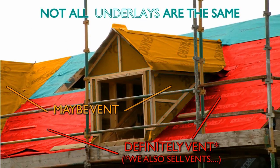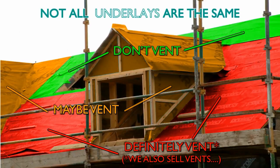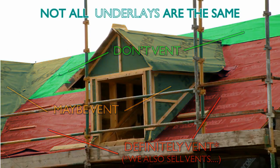Here we can see 3 different LR membranes installed on the same roof. While there is a lot in common, the specific product certification for each membrane will have subtle differences. So while all are broadly suitable for this application, the specific detailing required and the overall performance may vary considerably.